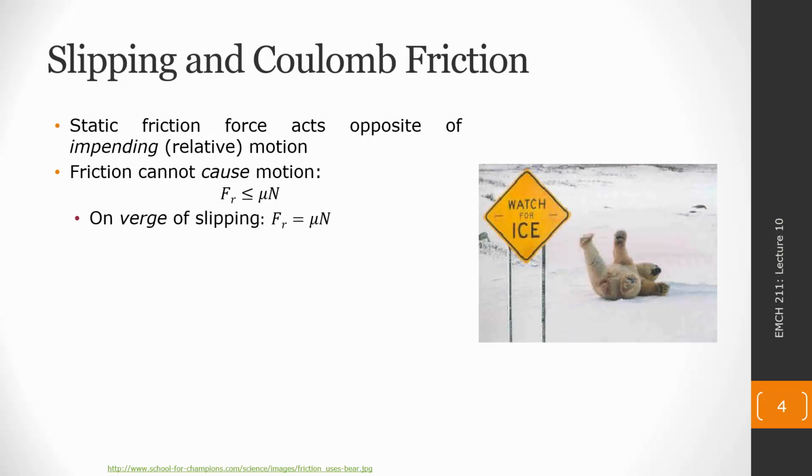Now, when thinking about kinetic friction in a dynamics setting, we have a very similar equation there, where the force of dynamic friction is always equal to mu times n in that case. But in a dynamic case, the mu is different. That's the coefficient of kinetic friction. And yes, when we are moving, in that case, our force of friction is constant. But for static friction, it is not. It is capped at mu times n.